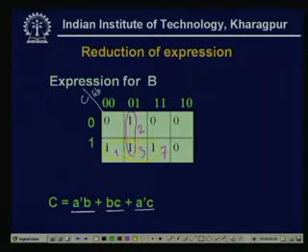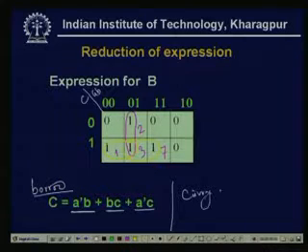See, there is similarity between the carry of the full adder circuit and the borrow of the full subtractor circuit. Only the min terms are slightly different. There the carry C was AB plus BC plus CA.